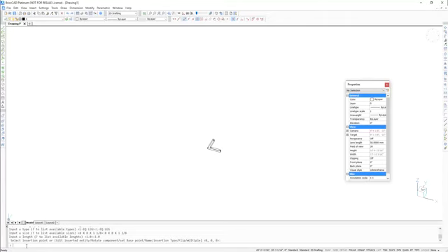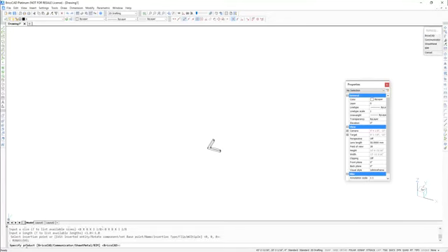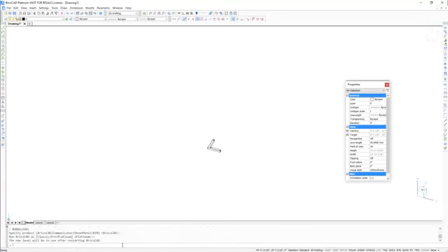There's a command, it's called run as level, and if you just type that at the command line, you'll see the different options here. If you choose BricsCAD, which is the default option, I'll just hit enter to accept BricsCAD, you'll see you can choose from Classic, Pro, or Platinum. By default, when you install the trial, it's setting you up for Platinum, but you can change that. If you type C for Classic, maybe you come from a 2D drafting environment, maybe AutoCAD LT, and you want to see how BricsCAD compares, you can set that to Classic. Now, do notice here at the bottom, it does tell you that you will have to close and relaunch BricsCAD for you to have that different functionality.